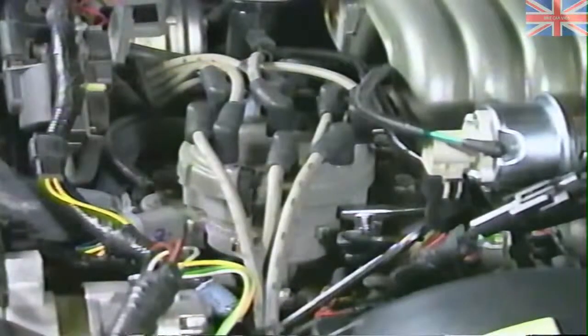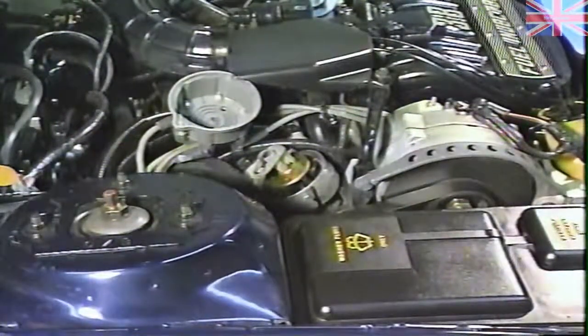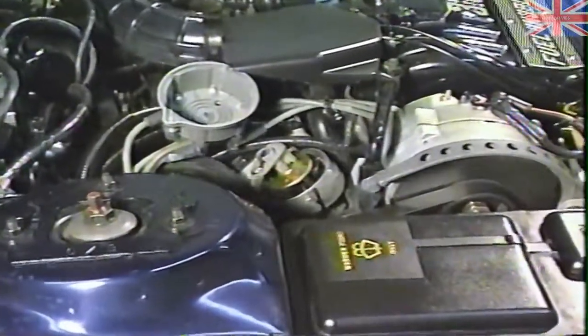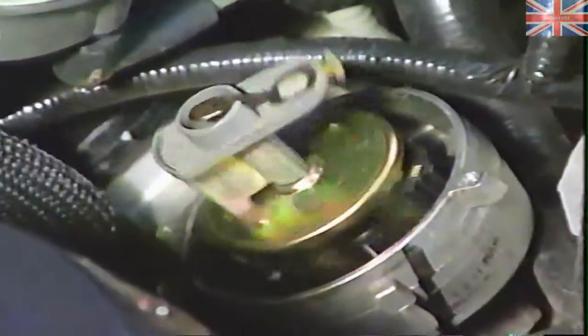The thick film ignition module is similar to the ignition module that you've seen for years on General Motors vehicles. It is a miniaturized electronic circuit with a switching transistor. It is mounted outside of the distributor case, either on the distributor body or in the cowl. The system uses no centrifugal or vacuum advance mechanisms. All spark control timing is performed in conjunction with the thick film module and the ECA assembly.